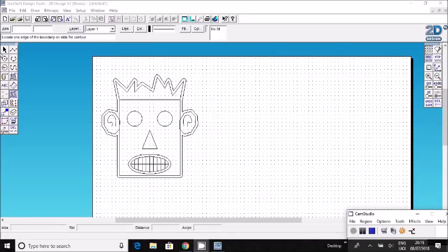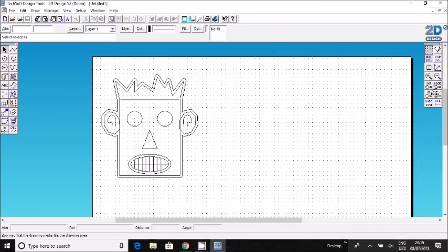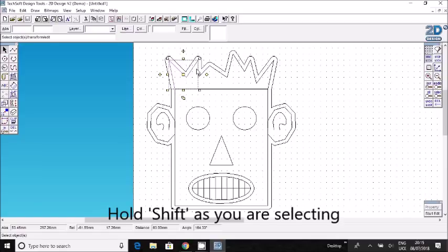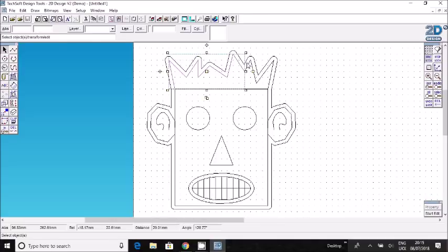Okay, so I'm now going to show you how to change the color of items. So if I zoom in a bit by clicking zoom all, I'm going to click on all of these lines at the top. So if you select one, that's just selected and it's turned pink to let me know I've selected it. If you hold down on the shift key now, you can actually select multiple items, and that's just by holding shift. So you could do that. When you've got everything selected and you're happy with that, if you go up to here it says col, that refers to line color.